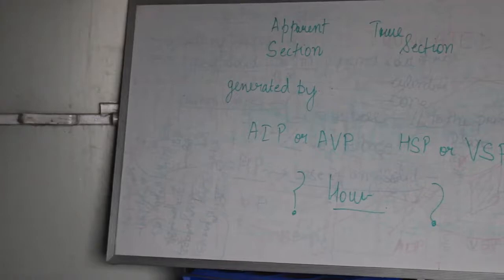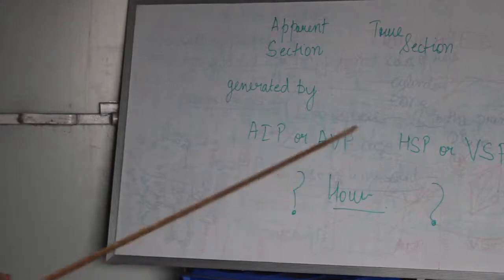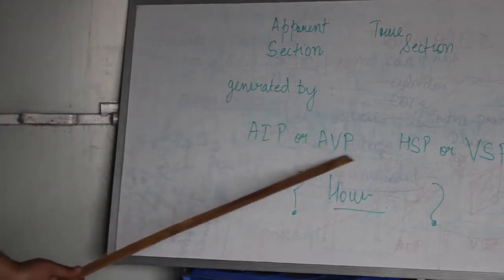Students, for more clarification on the subject where we have to use the cutting planes, the projections of the solid will be made on the principal planes, and if the projection is a front view, it is made on the vertical plane, and if the projection is the top view, it is made on the horizontal plane, right? So there are different types of sections which are generated after the solid is cut by the cutting plane. Now we have named 4 types of cutting planes here.